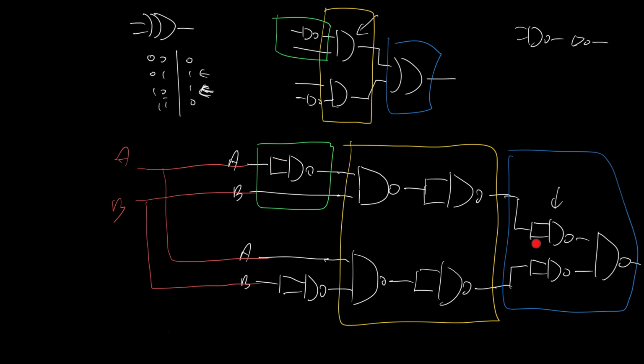And we've been able to implement this exclusive OR gate using only NAND gates. Now, do you want to do this in practice? Not really, because you can just buy an exclusive OR gate and it's going to be better in many ways, which we're going to learn about later on when we consider the transient response of logic gates. But this is a good exercise to show you not only a little bit about Boolean algebra, we talked about addition and multiplication, etc., but about the sum of product form and how, given an arbitrary truth table, we can implement it using only NAND gates by going via the sum of product form.